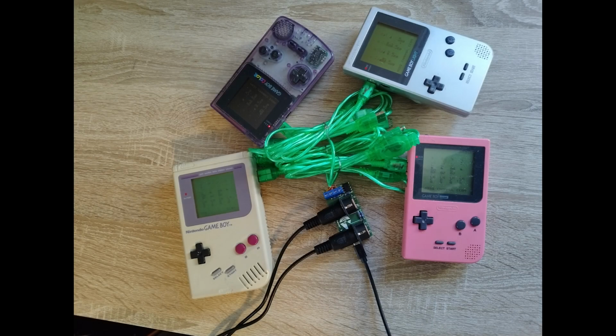So that was that. As you can see, the actual effort of creating a single interface link system for 16-channel MIDI playback across several interconnected Game Boys actually turned out to be surprisingly manageable. More than that, the single interface link approach has also managed to improve on pretty much all shortcomings of the previous multi-interface link system. It's easier to build, it's easier to use, and it's now possible for you to dynamically switch the different channel generator assignments on the go.